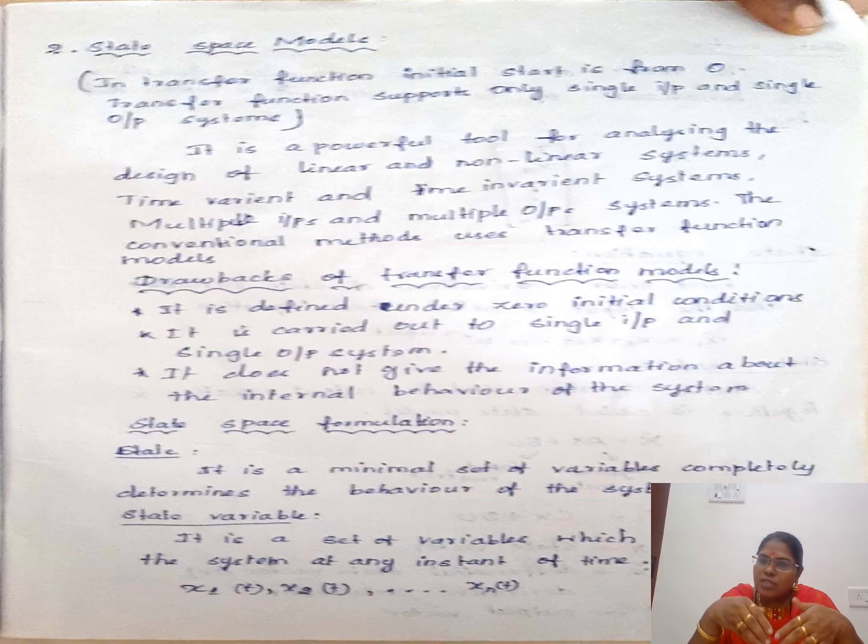Once it gets into the tank, I have to maintain the level of the tank, and it has to mix properly, so we have to maintain the temperature. So we need to apply various controls here, and each control I consider as one state variable. X1 is the state variable for flow A, another for flow B, and then the level of the tank and the temperature.